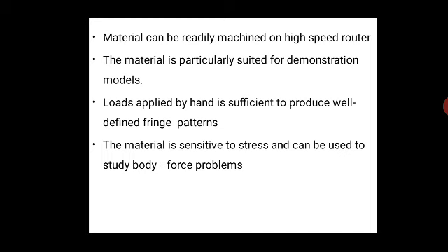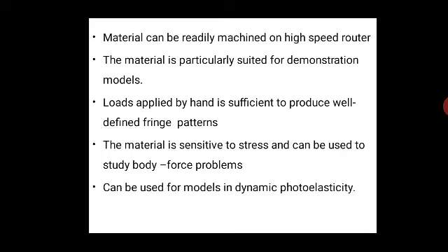Therefore, the selection of a suitable material for preparation of photoelastic models forms an important step in the photoelasticity analysis. And it is difficult to find a material that satisfies all the requirements. However, some of the important properties of an ideal plastic material are classified